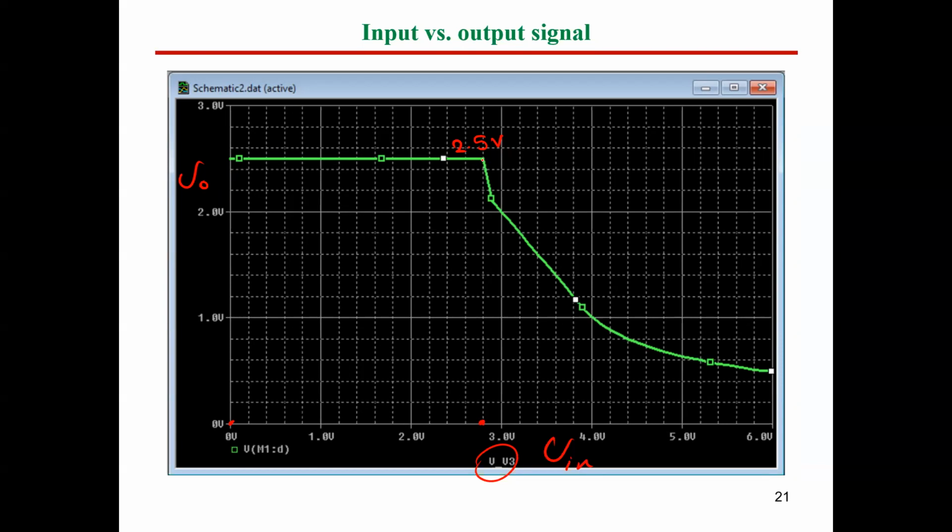So again, guys, the active low and active high limits or values may be different from one IC to another, from one MOSFET to another. So for any kind of IC, we need to check what the active high levels or range and active low range are. Nice. And for the voltage greater than like 2.8 now, the output volt is decreasing until reaching almost 0.5 or less. So the volt here is around 0.5 volt.